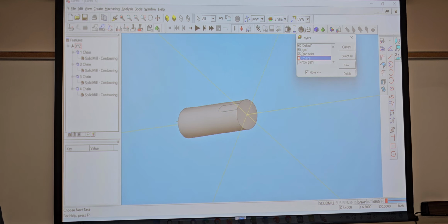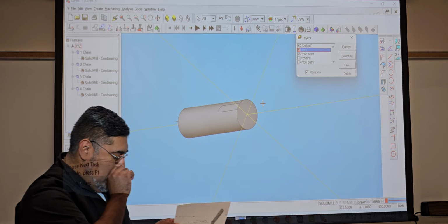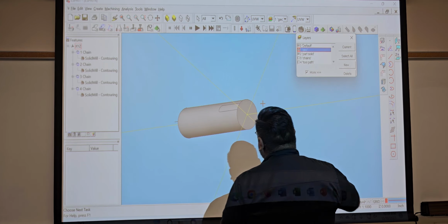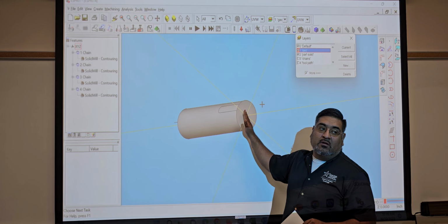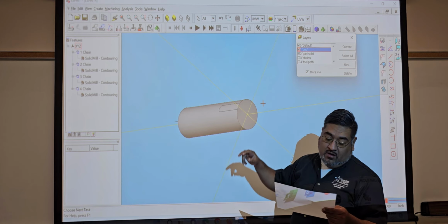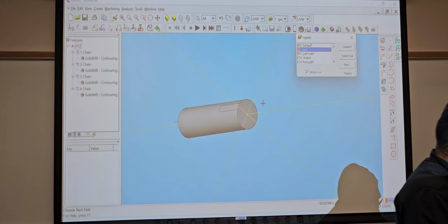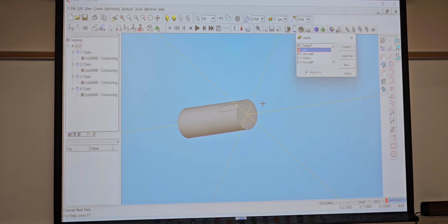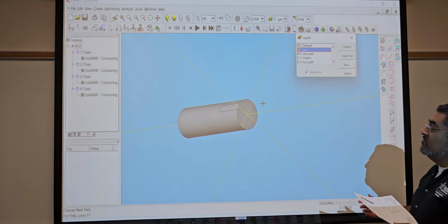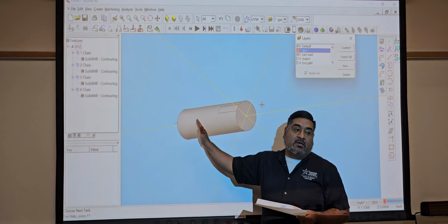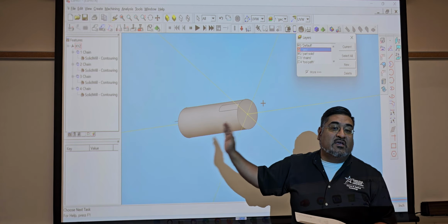I think there's only one way to find out if it actually crashes. All right, so for this groove, what I'm gonna do is make my work plane on my face, then draw a circle of the diameter of the groove. So if that's 250 coming down there, we have another 250 there, so that's half an inch, top and bottom, correct? So that circle is gonna be 2.5, correct? So the circle that I'm gonna make is 2.5, then I'm gonna translate it back.